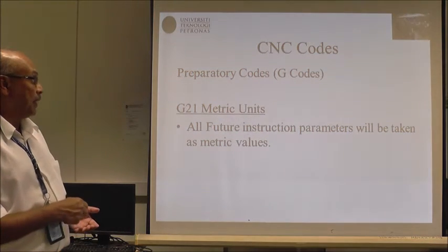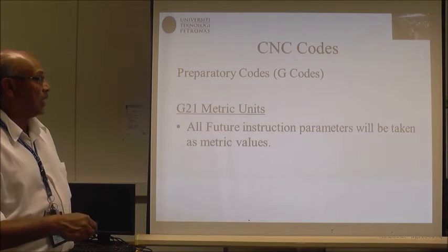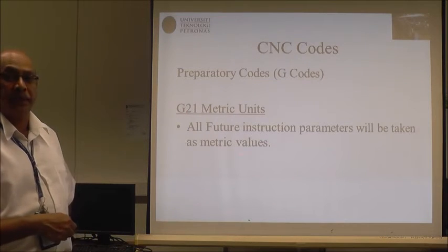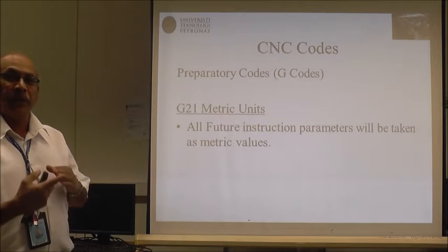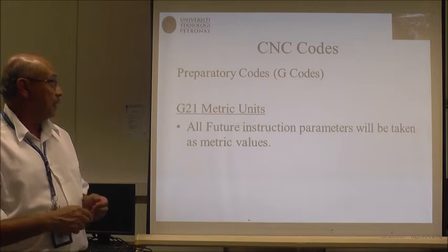So if you specify in your program G21, meaning all the X, Y, Z values will be taken as metric. So the X coordinate, Y coordinate, Z coordinate are all in mm. Okay. Alright, next.